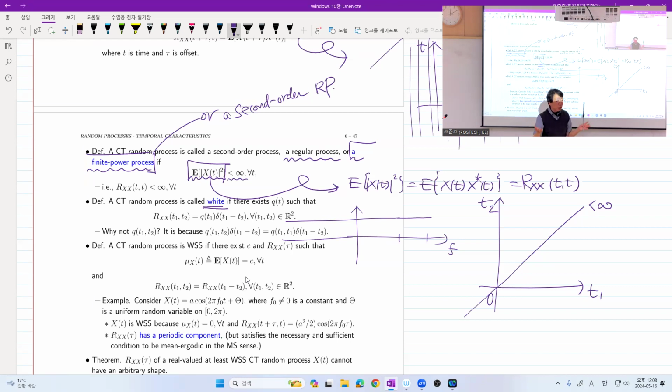No relation at all, right? If you have a finite band limited signal, what happens? What does that mean? If you take samples at the Nyquist rate, then you may say that I have no idea what will happen. However, if you sample faster than the Nyquist rate, actually, you can predict what will happen.